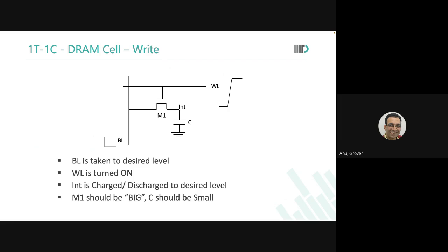So the word line is boosted, driven to a higher level than regular VDD. We talked about charge pumps at the time of the negative bit line. Variants of those charge pumps will be used in the DRAM also to boost the word line. Are you able to see this? You will notice that there are lots of small nuances which you need to understand so that you can know the topic well.